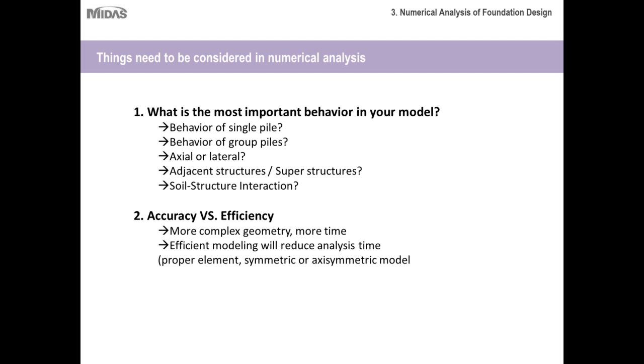So once you find the answers to these questions, you can then narrow down to the approach. Let's say the answer to the first one was that the behavior of a single pile is important for calibrating my model. But I'm dealing with a pile raft foundation, so it's not just a group effect, it's a bigger picture. Since I'm dealing with a pile raft foundation, I'll expect huge axial force or vertical loads onto the pile, so definitely I must go with a 3D analysis.